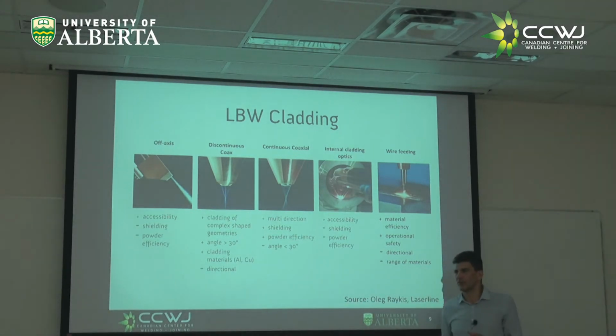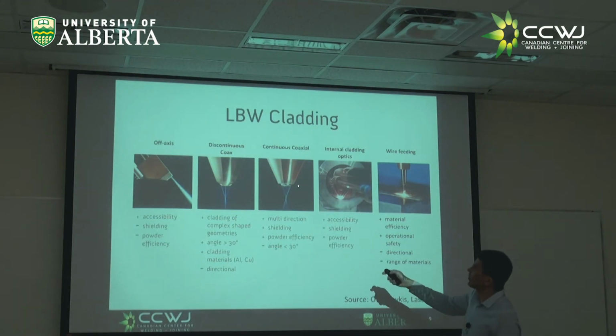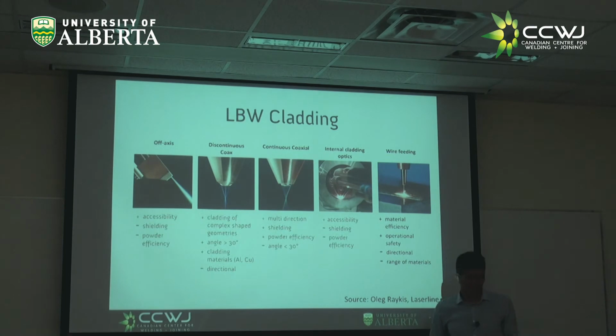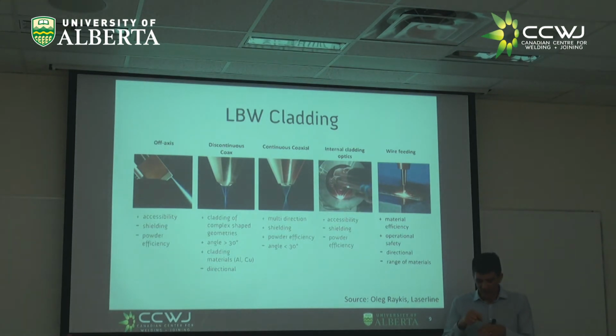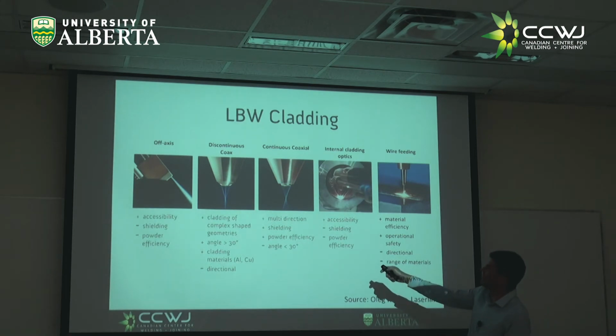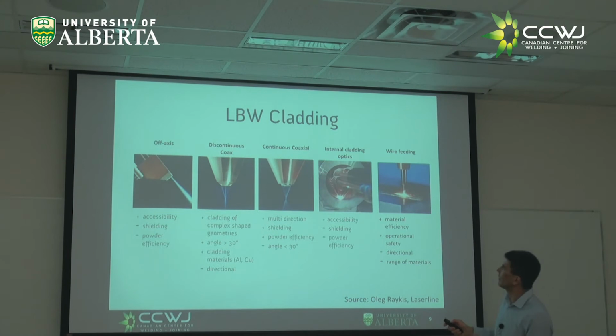You realize this is very difficult to set up. Very difficult to set up. These are called continuous coaxial. Sometimes continuous means it is continuous: you have an annular region that blows the powder. Sometimes in reality continuous means many, many holes through which you blow the powders. Right, so all these types of things we have going.